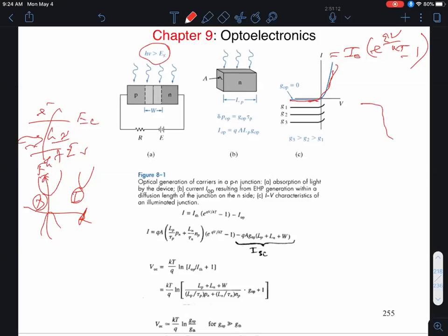So what you have is, if that's my reverse bias PN junction, say, in high reverse bias, we said that you have a few minority carrier electrons on the P side, a few minority carrier holes over here that diffuse to the depletion edges. And if I have a reverse bias, they get swept right across, regardless of what the reverse bias is, because it's not governed by the drift velocity. It's limited by the supply of these minority carriers, right?